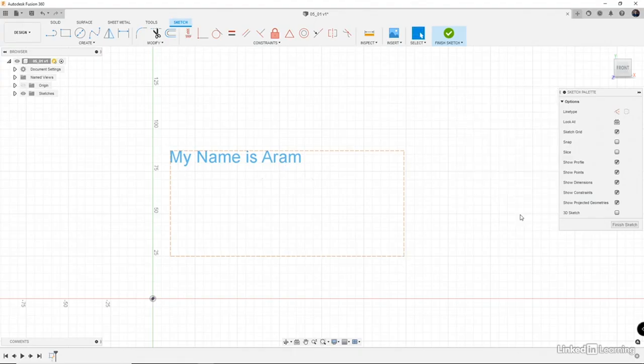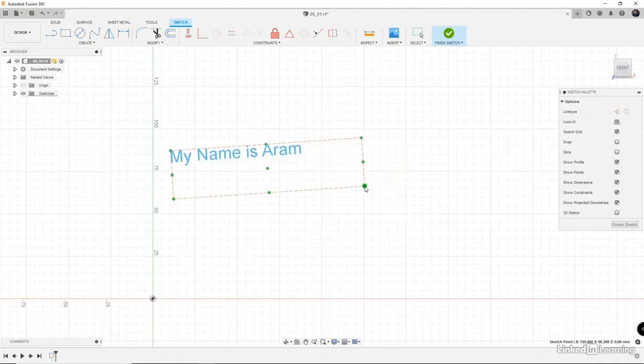So let's go ahead and hit OK. And now we see that all of this construction geometry is fully editable. So we can actually angle it, we can move it, we can do all kinds of things with this. Now, let's see how we can use some basic lines and some tools to drive some of these characteristics of the sketch. So one, we could actually define these boxes.